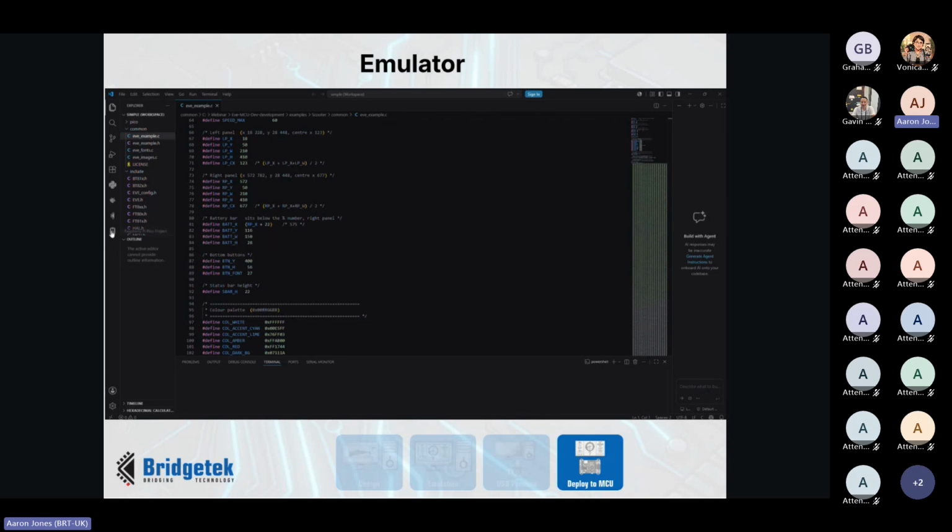This opens in VS Code, which has the Raspberry Pi extension enabled. You can also build using the command line Pico tools. Once the workspace is fully opened, we can run a cmake clean followed by a compile.